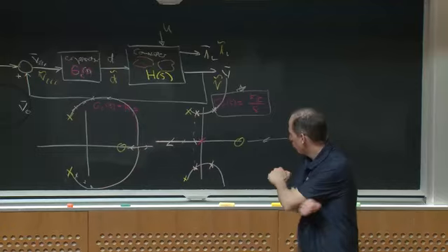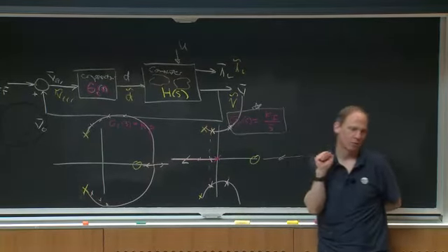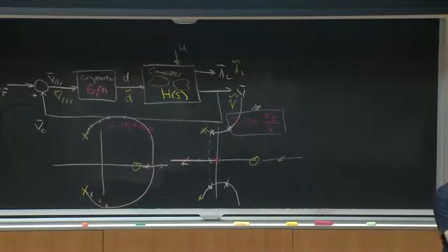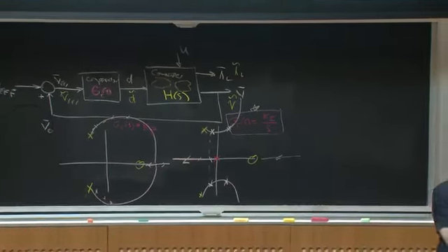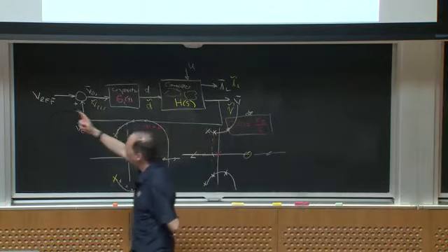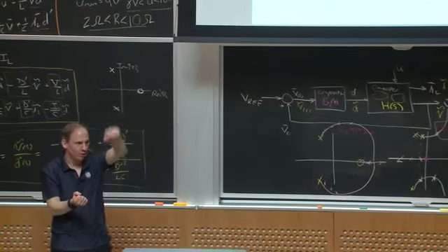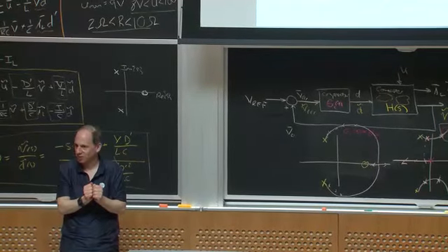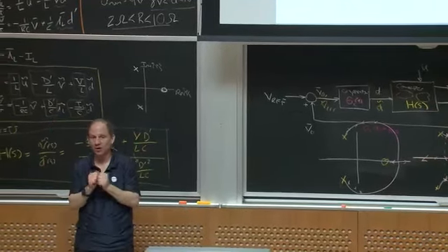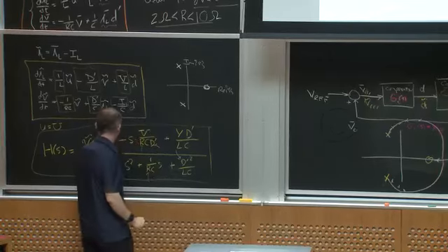One of them, if I just wanted to use something like an integral controller, or a more fancy version that's not just an integral controller, but something that was a good duty ratio control scheme. One thing I could do is change my plant so that it had friendlier dynamics. I already said if you don't want the voltage overshoot, I ought to use a bigger capacitor, right? I can also do things to the actual converter to make it friendlier for my dynamics.